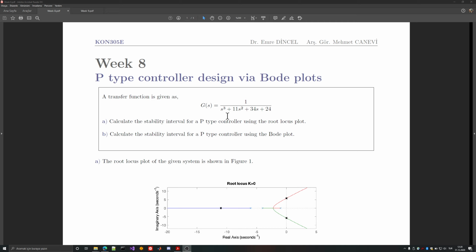Because this is a frequency method, the practical correspondence here is that you have a system. This can be a black box, or a system that you know the model of, and what you're doing is basically applying a sinusoidal wave as an input with gain 1 and phase 0.